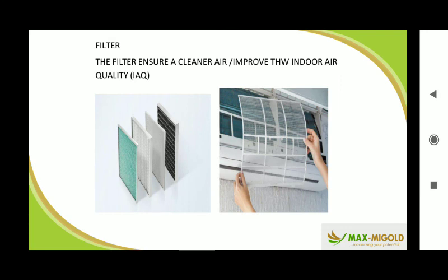Then another component that needs to be taken care of, which is the most important thing towards the quality of air within the space, is your filter. This filter also works exactly like our nose. If you check your nose, there are hairs just around your nose. What does the hair do? They try to block dust going into our body. The same way with your filter. Any dust going into the unit, the filter is the first point of removing the dust, getting a purified air across the coil, and supplying you with the required cooling.